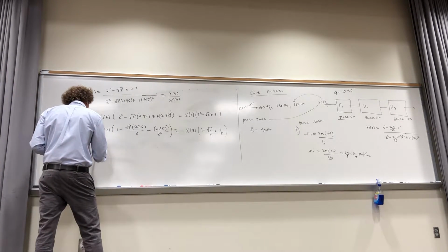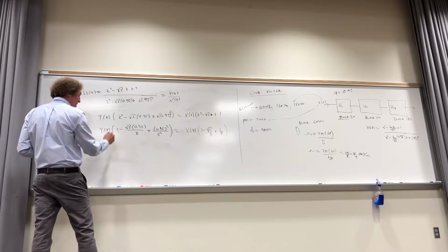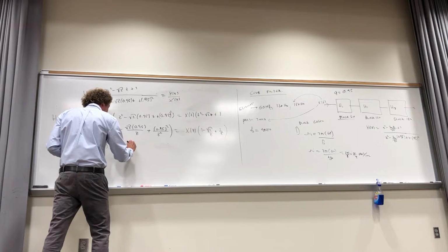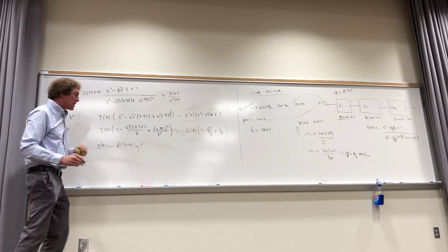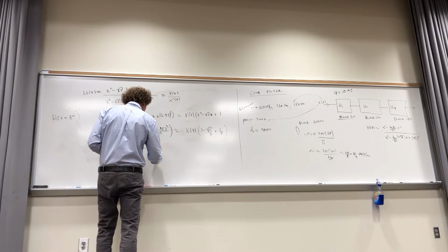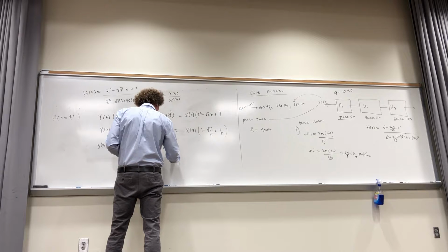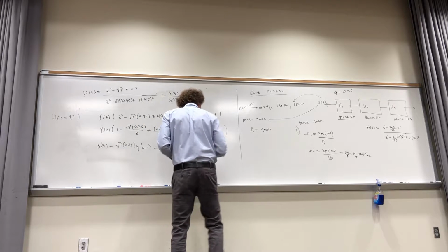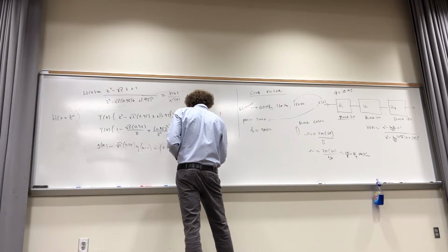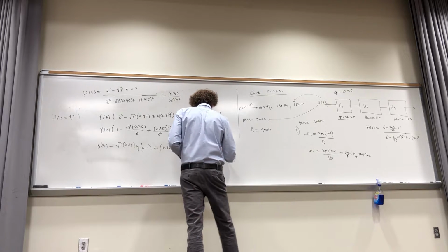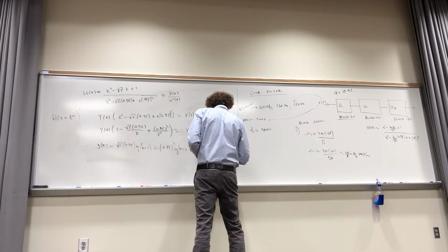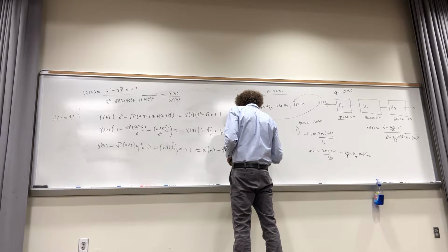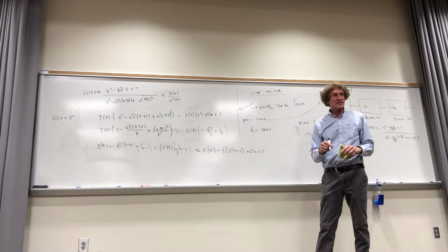Now, last thing we have to do is take this and put it into a difference equation. Let's just do it for the record. We have y of n minus square root of 2 times 0.95 times y of n minus 1, and finally plus 0.95 squared times y of n minus 2. Right, this is going to be important. We'll see why in a second. Then that equals x of n minus square root of 2 times x of n minus 1, and finally plus x of n minus 2, correct? That's the difference equation we're going to implement.